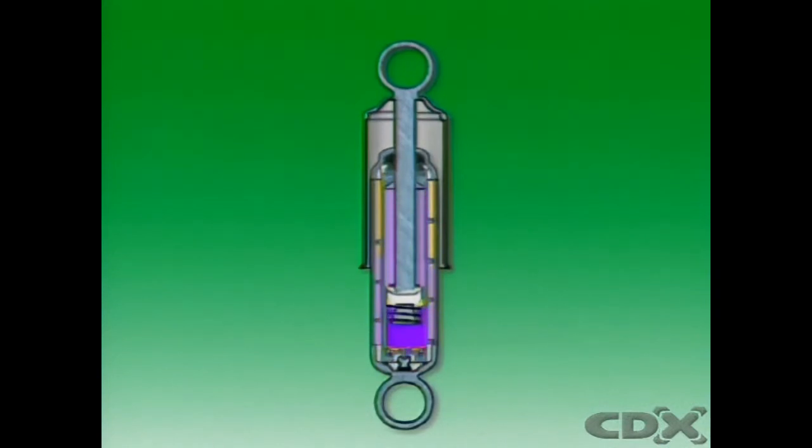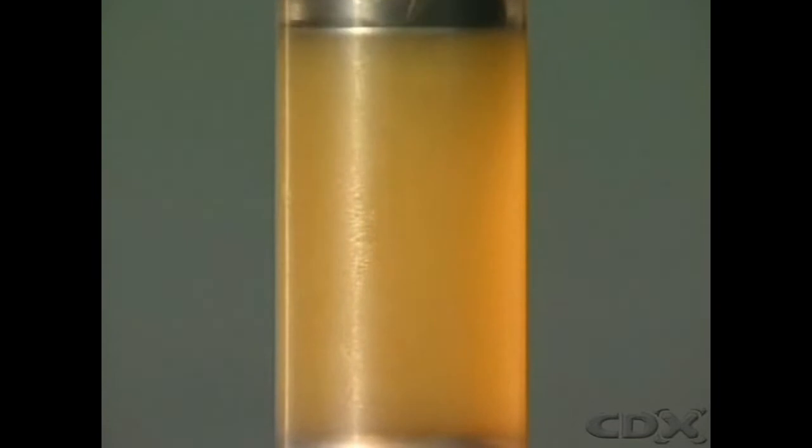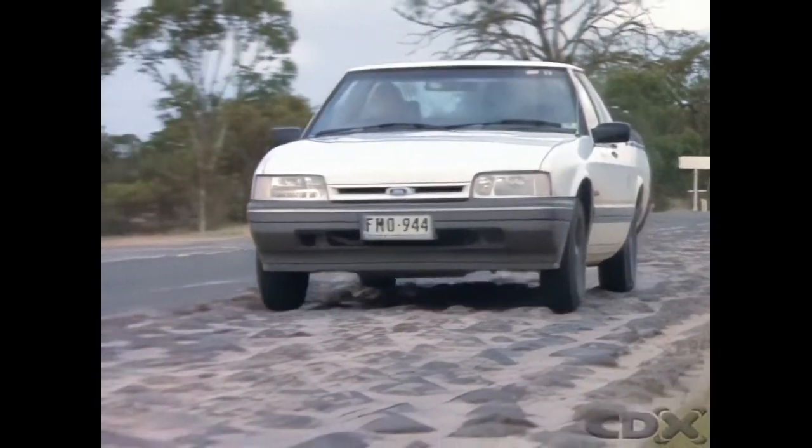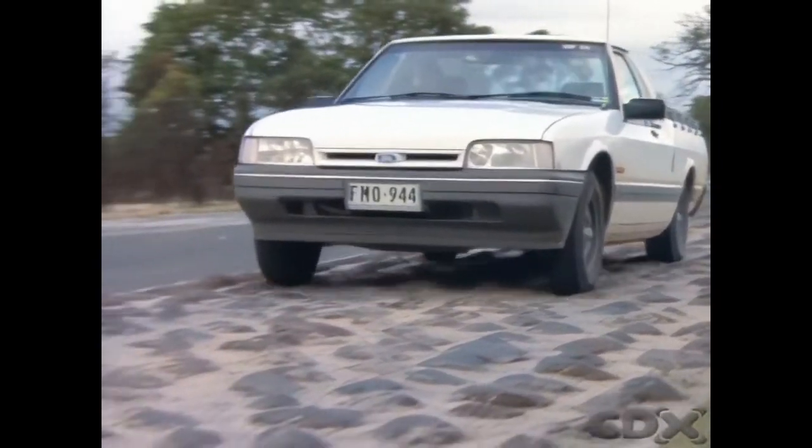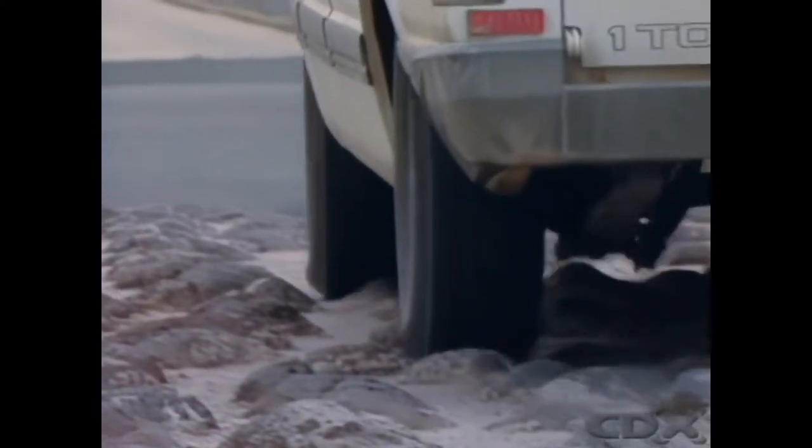In a hydraulic shock absorber, the oil heats up as the energy of motion of the suspension is dampened. The rapid piston movement as the vehicle moves over the road causes the hydraulic fluid to aerate. This reduces the dampening effect, and the shock absorber's performance very quickly deteriorates. This condition is called shock absorber fade. It can be reduced substantially by pressurizing the fluid with gas, usually nitrogen.